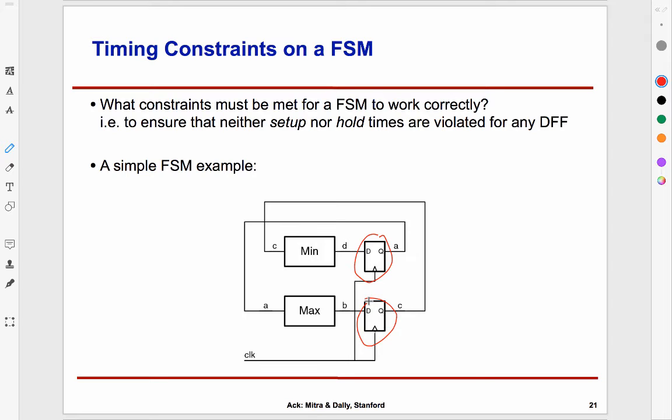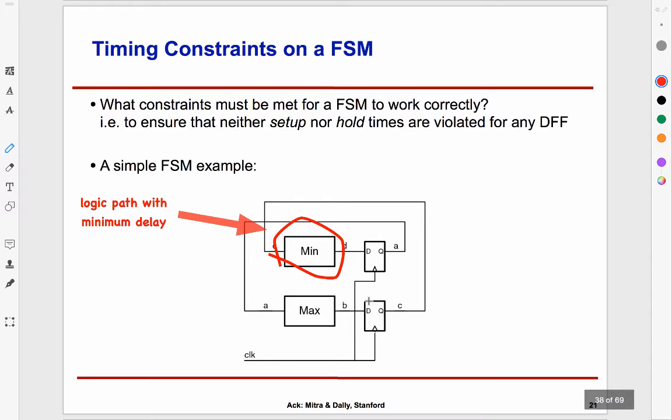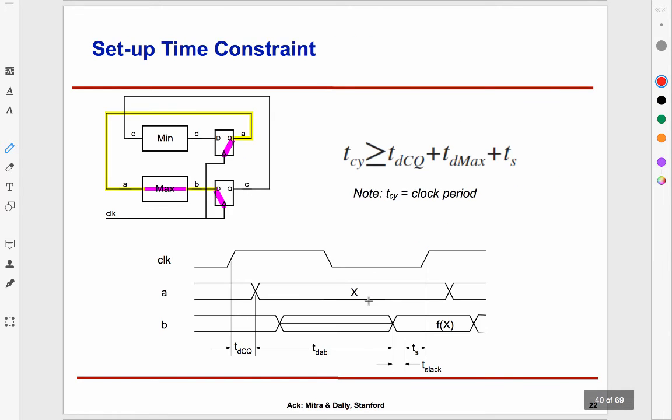So remember what we said. We said that at the clock tick, the flip-flops take the new state. And that happens at every clock tick. At every clock tick, they update the state, it propagates, the next clock tick happens. And these are logic delays. Okay. So now let's think about how setup and hold times play out.